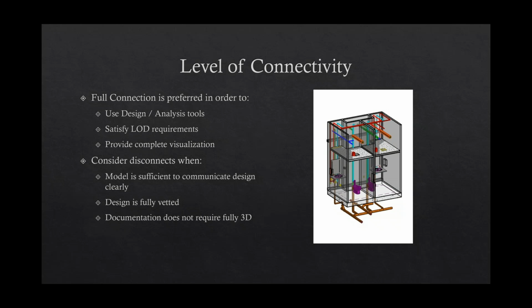And also it depends on what you want to do with your visualization. If you want to be able to create a 3D section like this one, you need to bring it at least close to its installation point to have it represent properly. But if it's purely going to be used for creating a 2D drawing, you might have the luxury to say you can bring the pipe in plan over it and then terminate it there and have it look right in plan view, when in 3D it might not be fully connected.